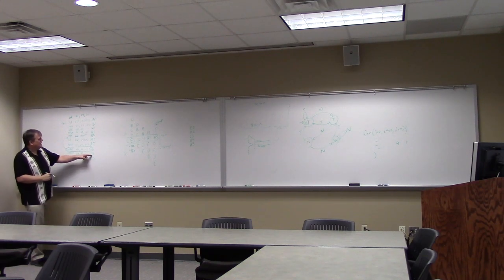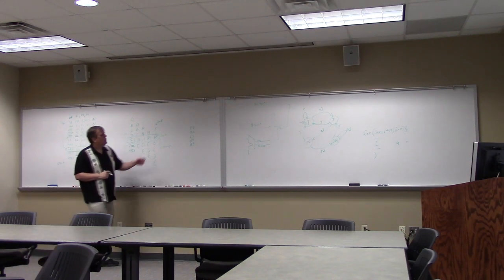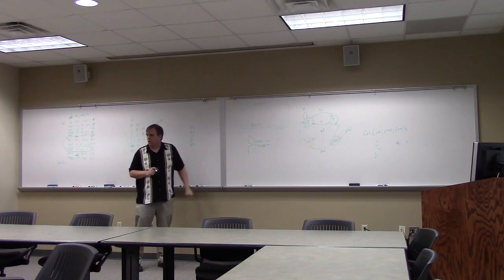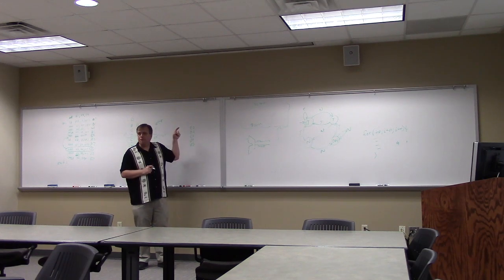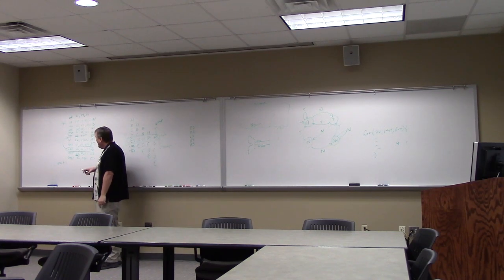So I don't want D2 to mess up E1's value of T2. Can it? E1 finishes before D2. Or at the very least, E1 is going to start before D2 is going to start. So since E1 starts before, it'll fetch its values before this one even starts fetching its values. So can D2 finish before E1 fetches its value of T2?